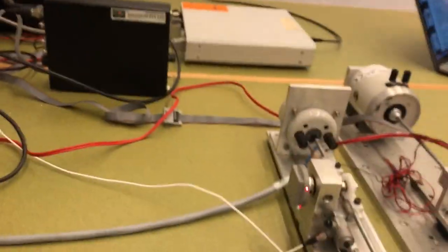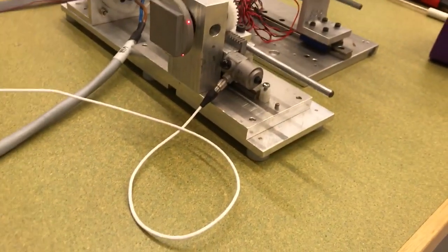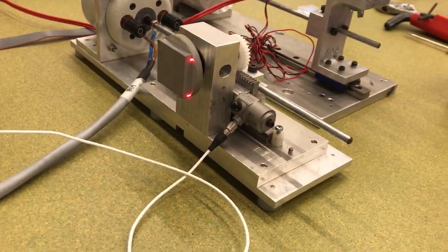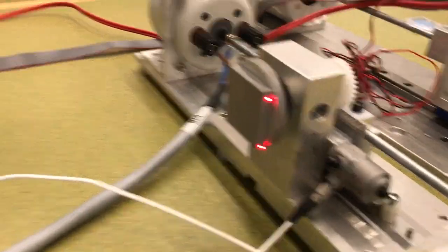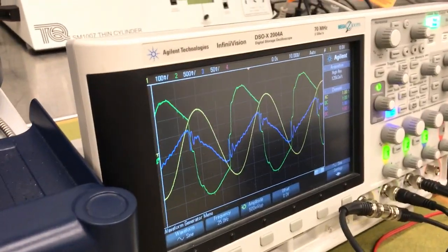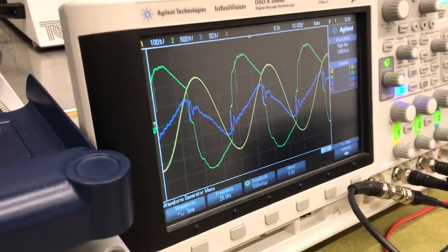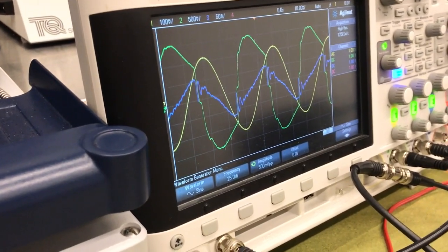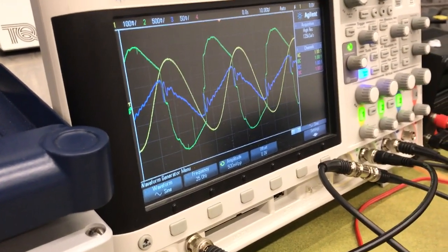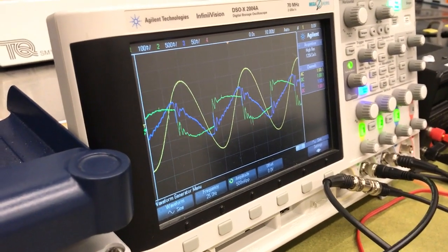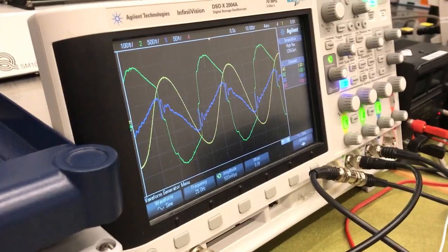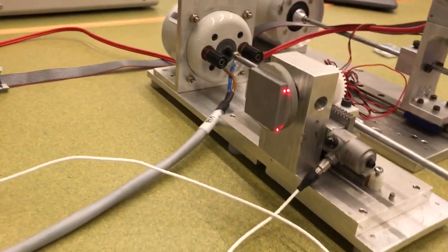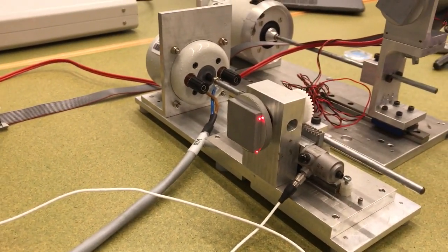We can also, with this instrument, take measurements from square cross-section as well as an angular cross-section. So if I move the beams over onto the square section, you can see that there's essentially no sensitivity to cross-sectional shape variation. Exactly the same signal if I move them across from circular cross-section to square cross-section. The beam falls off a little bit, but once the beams are stable on the wheel, I get a good measurement of angular vibration. Now you have all of the